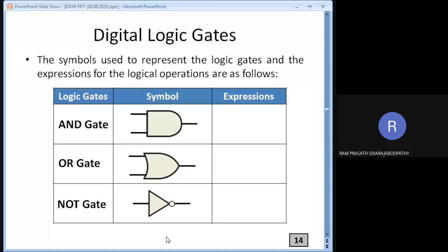Okay, fine. So for the AND gate, there are two inputs here and one output. We can have many inputs, but we have only one output in the case of AND gate. Here the example given is a 2 input AND gate. You can also have 3 input or 4 input like that. The expression is C is equal to A and B. AND operator is dot. As I mentioned earlier, A dot B, that is A and B, logically ANDed the value of A and B.